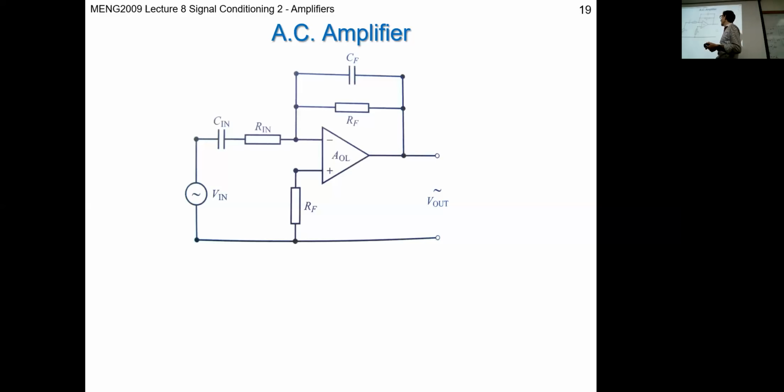But because it's varying, your whole circuit will be continually in flux, right? So as voltage goes up, you get an output rise in voltage and decrease in voltage. And what you need to build into this circuit is some way of storing and discharging charge, which is why you have capacitors, right?